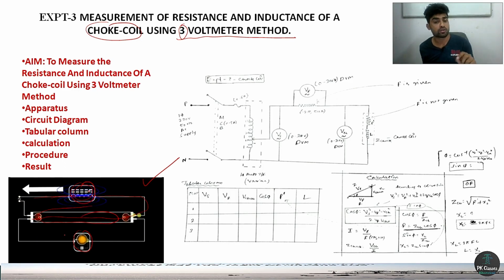And also the choke is there to induce high voltage at the time of starting. See, from here to here there is no connection, right? Electrically it is not connected, only gas ionization. So high voltage is required at the time of starting for energizing the ions, I mean argon will be there inside, mercury vapor will be there. For that purpose we need high voltage for a short interval of time, right? Once the lamp is glowing, after that the starter is not required, right? So electrons will move here to here, here to here once it is energized, right?